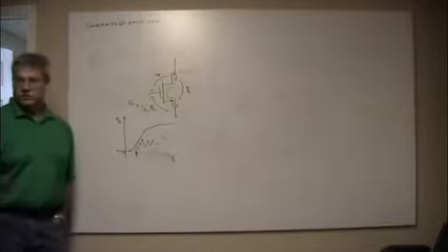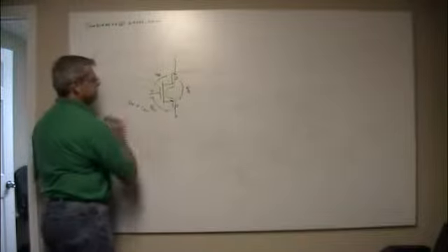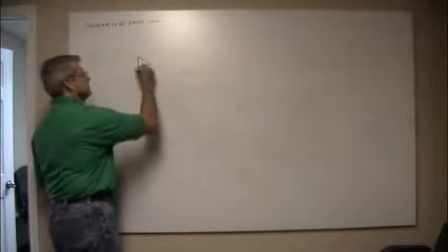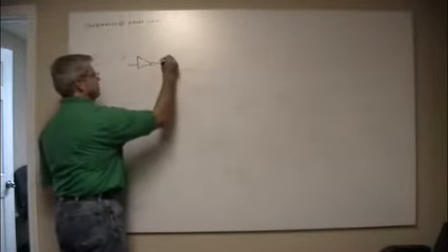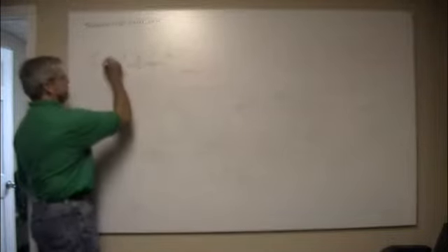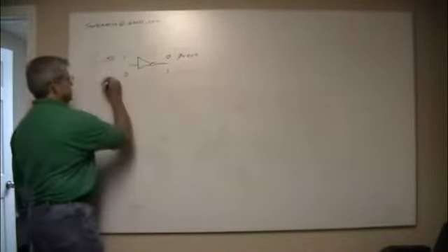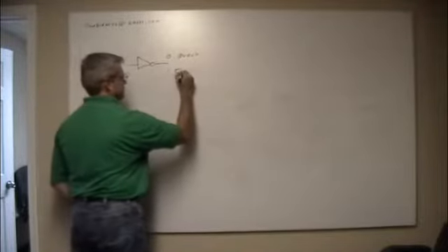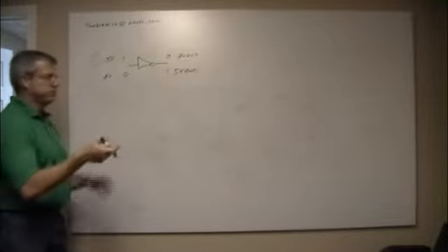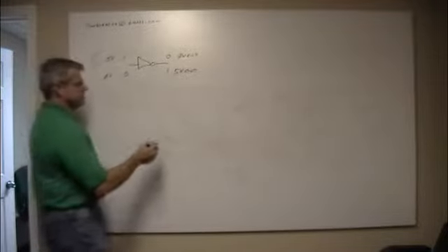But what we use them most for is switches. The simplest logic gate inside has this symbol. An inverter: a 1 in gives you a 0 out, a 0 in gives you a 1 out. Logically speaking, this would be 5 volts in giving 0 volts out, and 0 volts in gives you 5 volts out. We use digital binary, and we use binary math when we do the design for all these things.